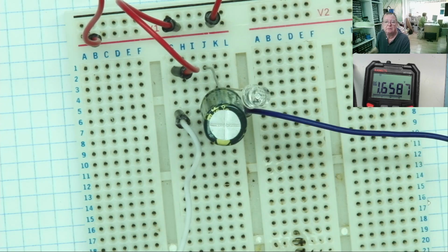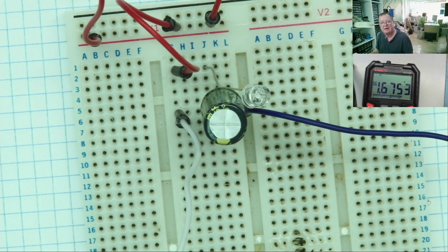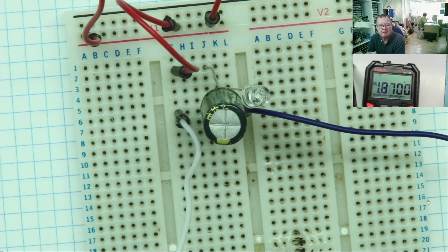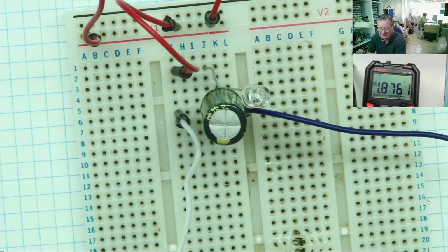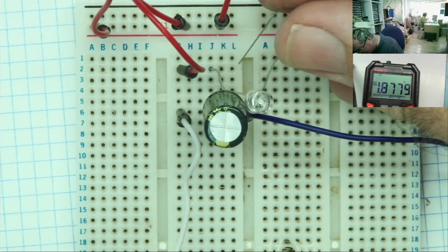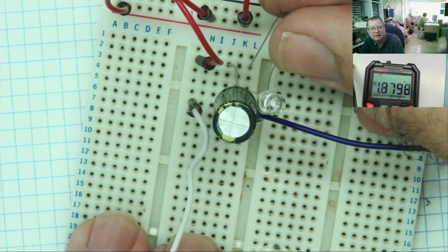Take this out. Notice, by the way, it now actually climbs up slightly. That's a strange property of capacitors called recovery. When you stop drawing current, it won't charge all the way up. It'll just charge back up a little bit, but hey, you may as well see it now, because otherwise it will just confuse you when you do see it later. That recovery effect with an electrolytic capacitor is in part due to the fact that there is a chemical reaction going on inside here, okay? Or rather, there are chemicals inside there.